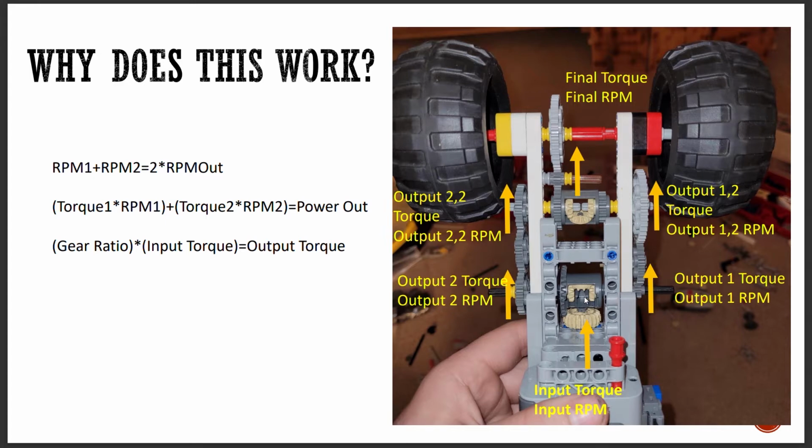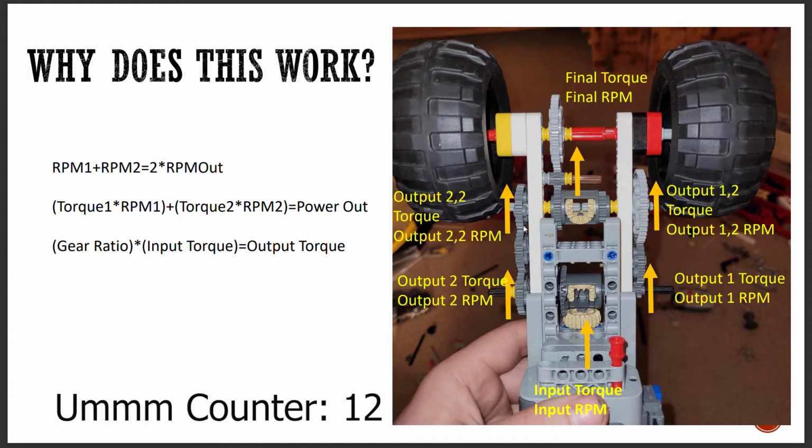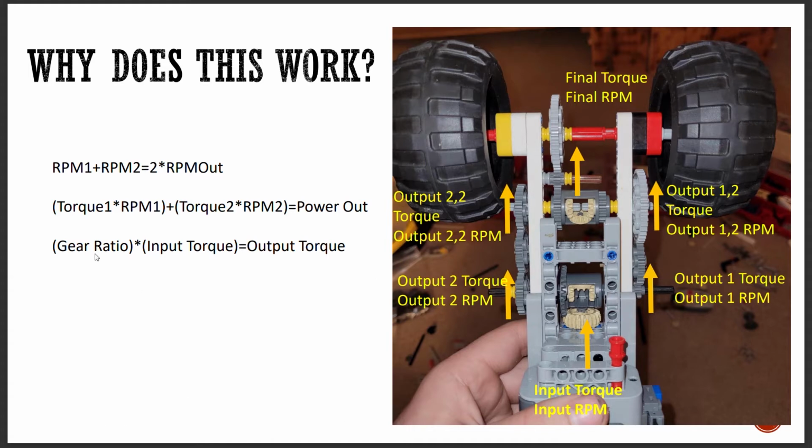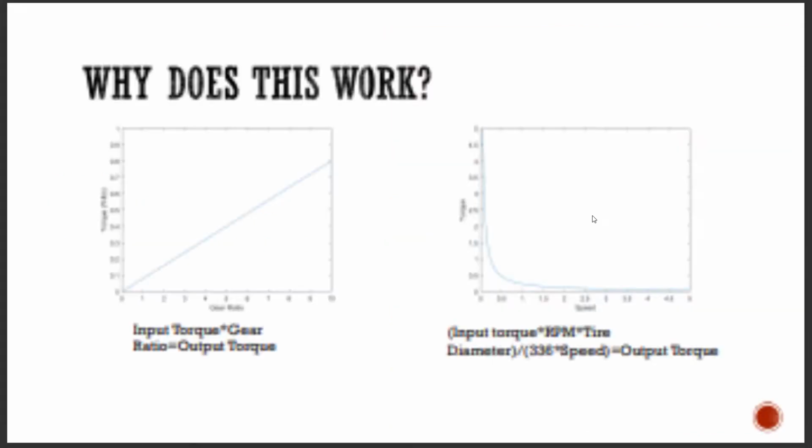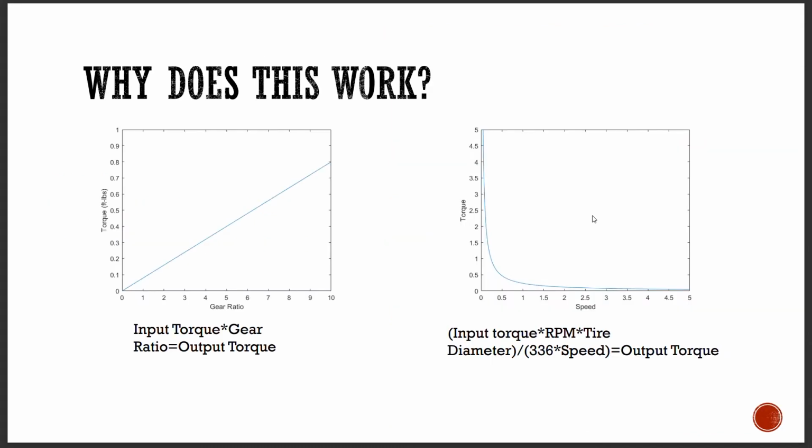Now, our gear ratios will change from each side of this initial differential. As you follow it down, we're going to get a split in torque, but then that's going to be multiplied out on different sides, given this final equation over here where we have gear ratio times input torque equals output torque. This gear ratio in this case is 1 to 1, so whatever split here is just what ends up here. And on this side, we're multiplying our torque out because we're going from a smaller diameter gear to a larger diameter gear. So on this side, this would be our first gear. On this other side, this would be our third gear. And because this function doesn't have any discontinuities in it, we will have a second gear where these will be running at equilibrium.